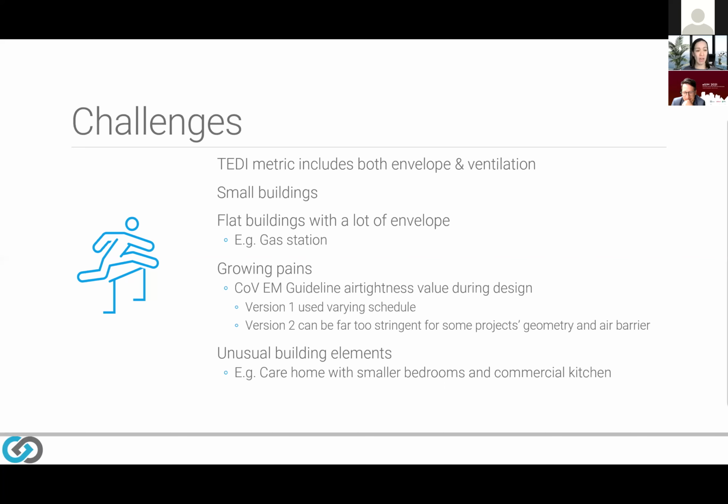So for example, hospitals have major ventilation requirements and very clear boundaries as to where there can be heat recovery and not. Of course, envelope is still important because if you have people stationary in beds by a window, you want to make sure that they're comfortable. But envelope isn't going to be the driving factor for energy performance. And so that's one of the ones currently under consideration.